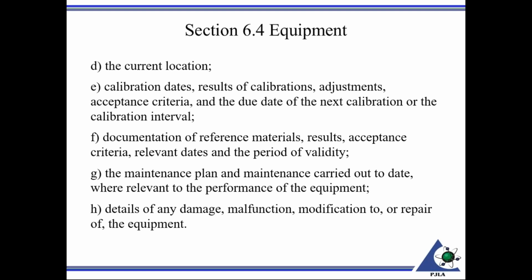Documentation of reference material, results, acceptance criteria, relevant dates, and the period of validity, the maintenance plan and maintenance carried out to date where relevant to the performance of the equipment, and details of any damage, malfunction, modification to, and or repairs of the equipment. Wherever these are applicable, you need to make sure that you have a record.